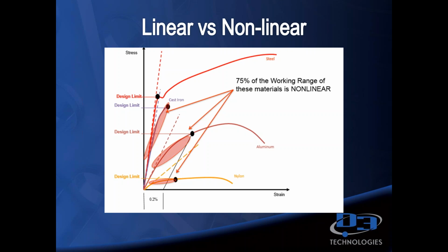So if I take a spring and I expand that or stretch it twice as long, it ends up exerting twice as much force. But Fusion can also get into nonlinear simulation, where materials tend to act in a fashion where the reaction of that material changes and has a curving stress-strain curve. So things like rubbers, some plastics, even certain metals like cast iron, technically aren't linear materials, and so Fusion 360 can handle a lot of these nonlinear materials.